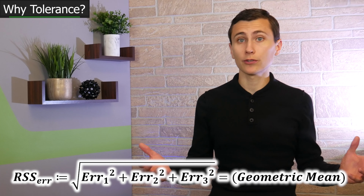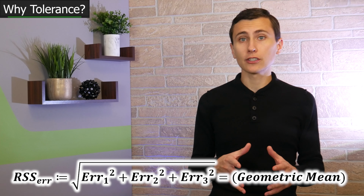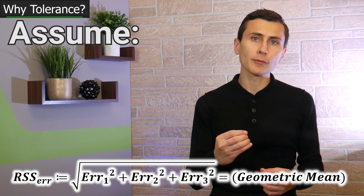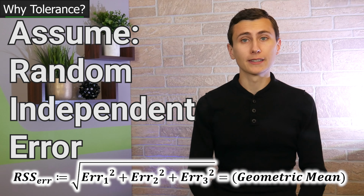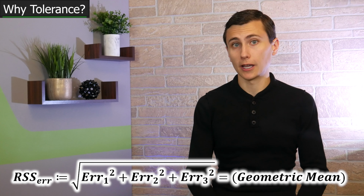Now, it's very unlikely that every component will be pushed to the worst, most extreme value all at the same time. So sometimes I'm going to roll up the individual error contributors using an RSS method, or root sum square. This error combination method is the geometric mean of all errors, and it depends on an assumption that the errors in a system are random errors. It's important to remember that because not all error contributors are random, like temperature effects. Temperature effects tend to skew all resistors in one direction all at the same time.